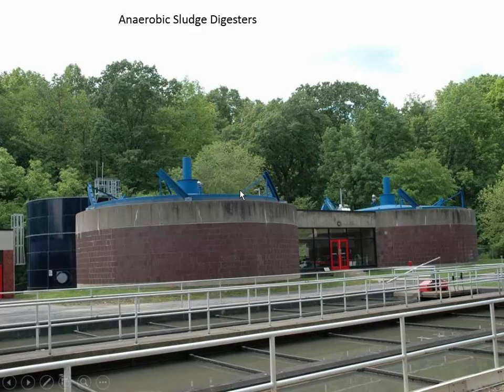You can tell when you're at a wastewater treatment plant where the sludge digestion is happening, because usually the tanks are open to the air. Like we've seen clarifiers and aeration basins, and they're always just open, the air is around them, the rain. If it's raining, it'll go into those things. But these have a roof on them. So if you see a circular tank with a roof, that's anaerobic treatment of sludge.